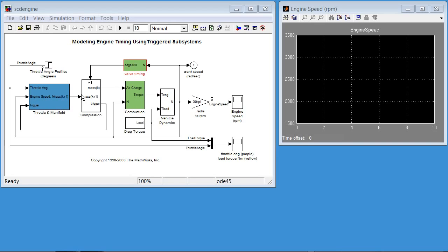You can do that by injecting sine stream or chirp signals into the input of the model, logging the output signal, and computing the FFT. All of this is automated using a GUI in Simulink Control Design or a couple of simple commands. Simulation-based frequency response estimation is also useful for validating the results of exact linearization.